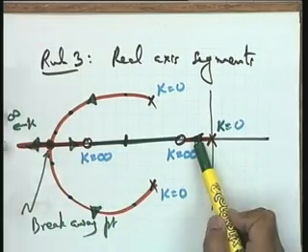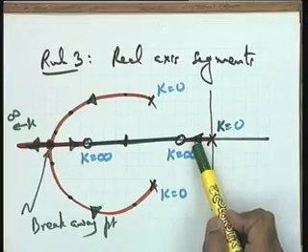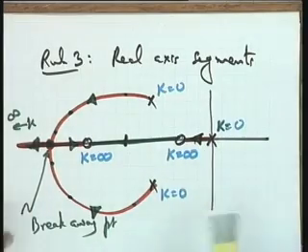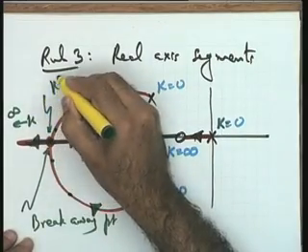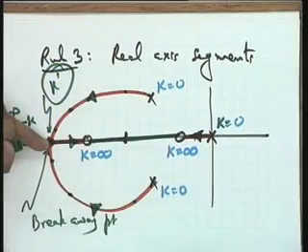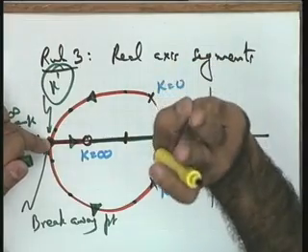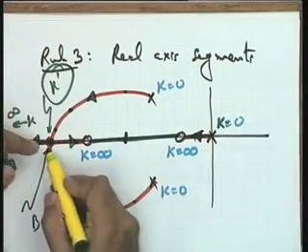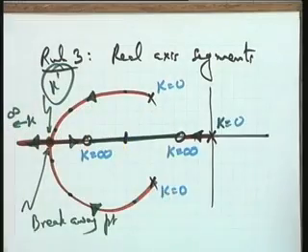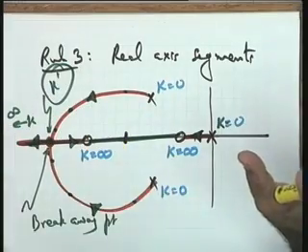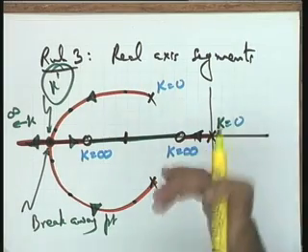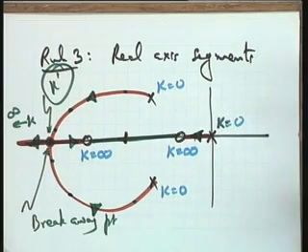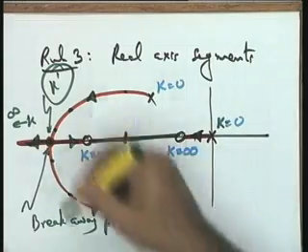Okay? This root is naturally real; it is a first order term. So you can just see what the closed loop system is. Till this particular value of gain, some value of gain k dash, you have two complex conjugate poles and one real pole. After this k dash, all three poles are real poles. The closed loop poles I am referring to, because the root locus plot gives you the closed loop poles only, where your starting point is the open loop poles of the function F(s). Is it okay, please? When the more complete rules come, the diagram will become clearer.